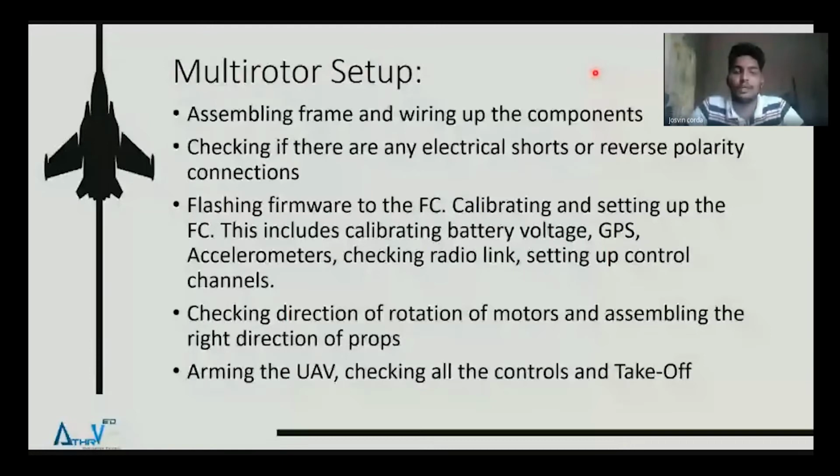If you have soldered the connection, some of the ESCs will also allow you to change the direction of rotation in the software itself. And then, depending on the rotation of the motors, you have to also choose the right direction of props. As in, if the motor rotates in clockwise direction, you will put a clockwise prop on. If anti-clockwise, you will put an anti-clockwise prop on.